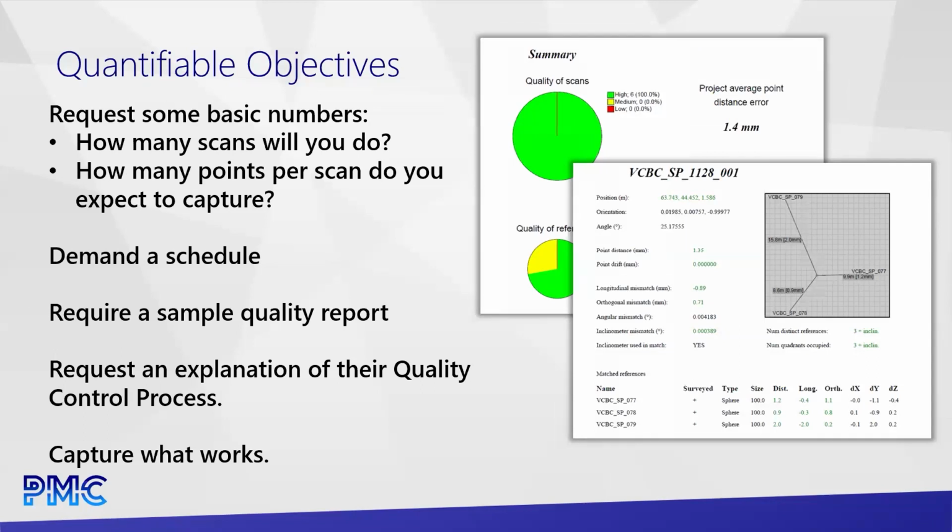How many scans will you do? What scanner settings are you going to run? So you know how many points you're going to capture. This is less important nowadays, the number of points, than it used to be, because all modern scanners are so fast that we capture probably more points than you need. But it's still worth asking. How many scans, as we talked about earlier, right? That's a critical one, because if I say I'm going to do 300 and someone else says they're going to do 100, you probably need to talk to both of us, because one of us doesn't understand what it is you need.